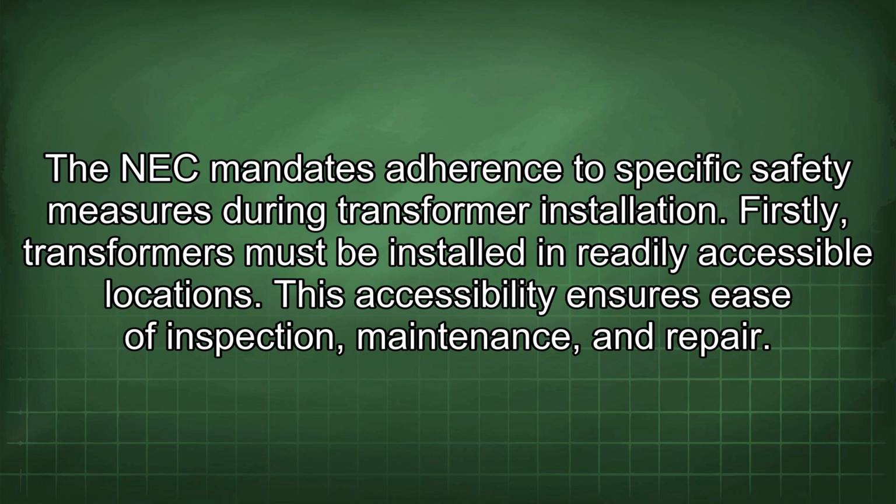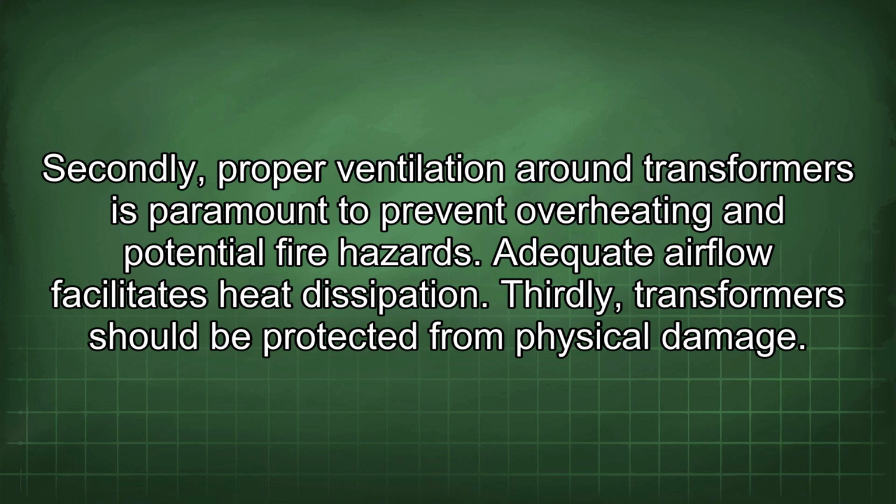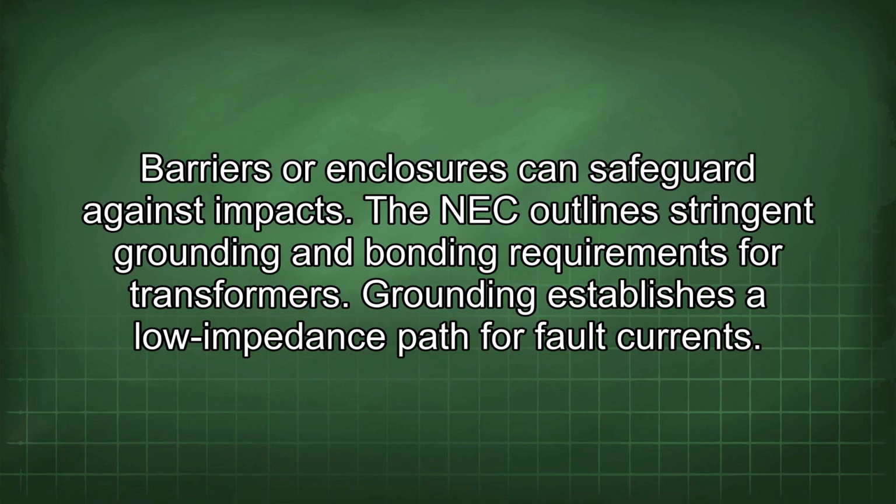The NEC mandates adherence to specific safety measures during transformer installation. Firstly, transformers must be installed in readily accessible locations. This accessibility ensures ease of inspection, maintenance, and repair. Secondly, proper ventilation around transformers is paramount to prevent overheating and potential fire hazards. Adequate airflow facilitates heat dissipation. Thirdly, transformers should be protected from physical damage. Barriers or enclosures can safeguard against impact.